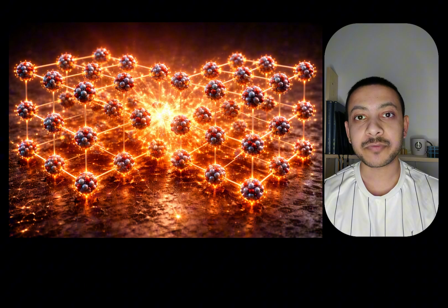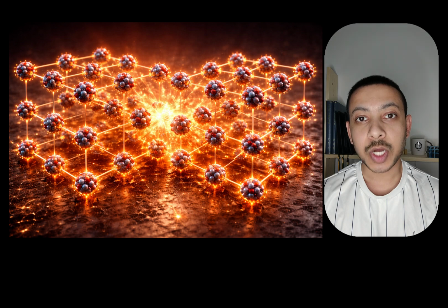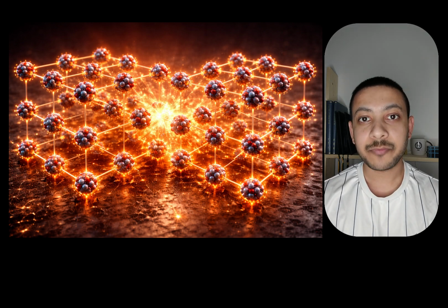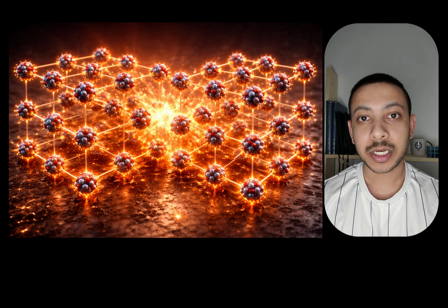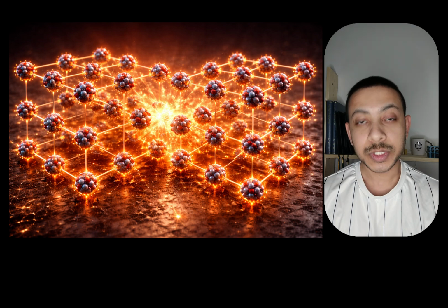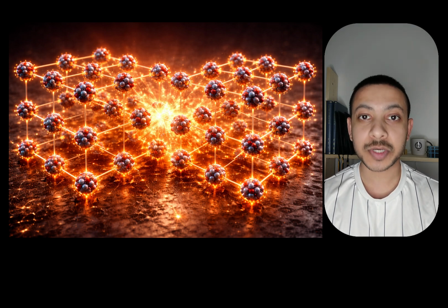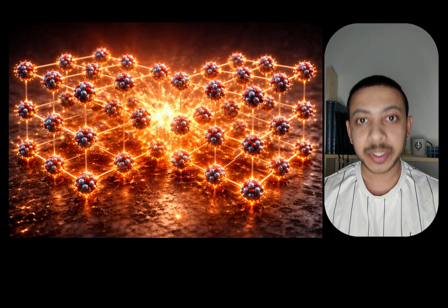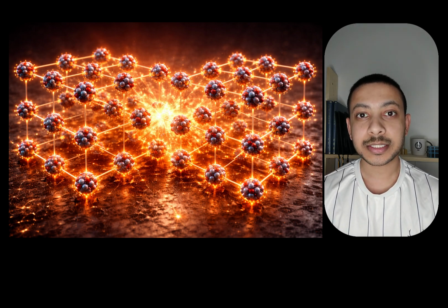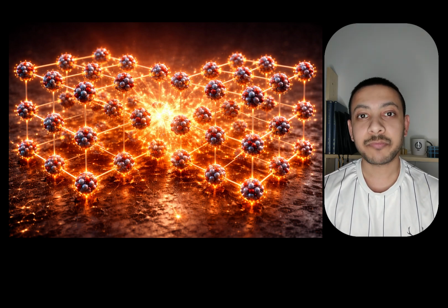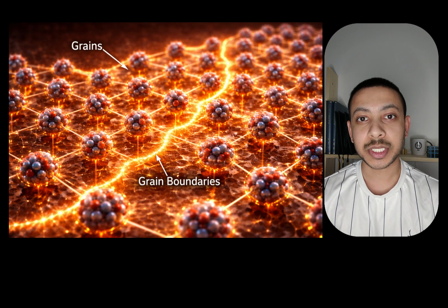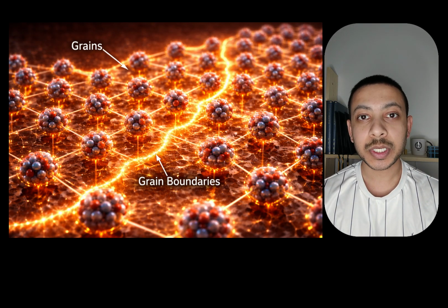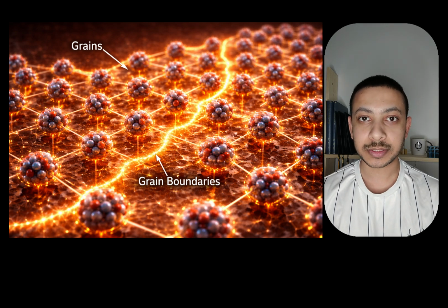And we may have another set of solid iron atoms that had formed at a different location along a different orientation, which may come together and join to the first set, thereby creating the structure as you see on your screen. In materials engineering, these sets where we have a defined unique arrangement of atoms are referred to as grains, and the boundary between these two is referred to as grain boundaries.